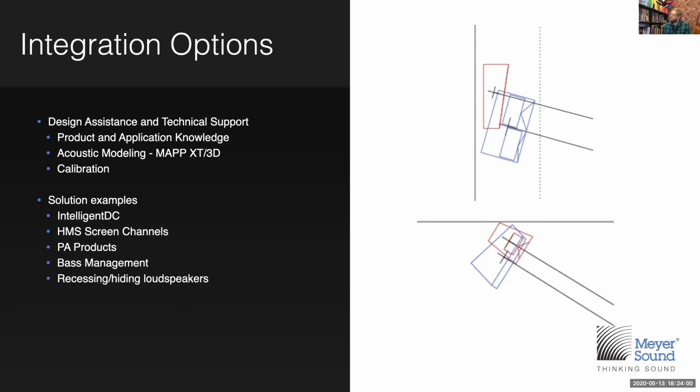In residences, oftentimes there will be a reduced space between the projection screen and the back wall. The top image I'm showing on the right compares an Acheron Designer to an HMS 12. Those should offer adequate SPL for a small home cinema, but you can just tell the depth difference we gain by going to the HMS. When we mention something like that, it comes with a few caveats: if you use that HMS, you're going to want to base manage because it doesn't have quite the frequency response of an Acheron Designer. But it can provide some wins for architectural points.